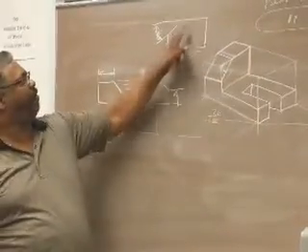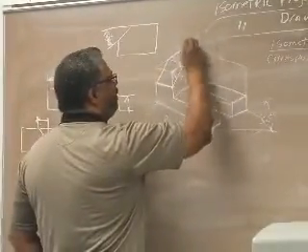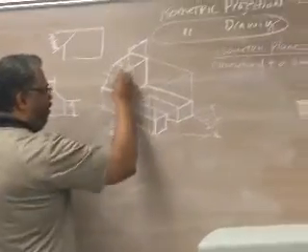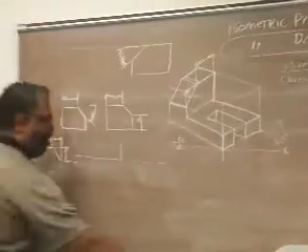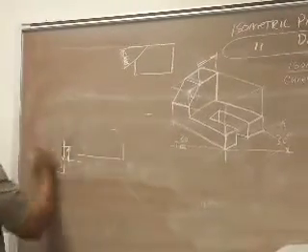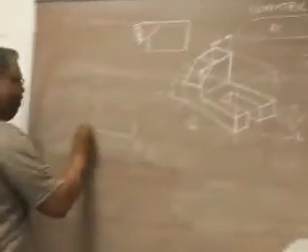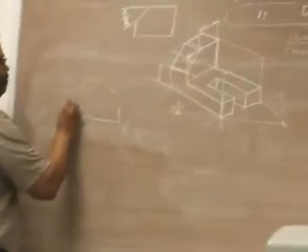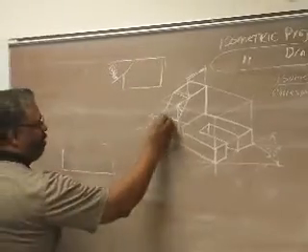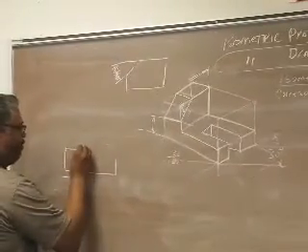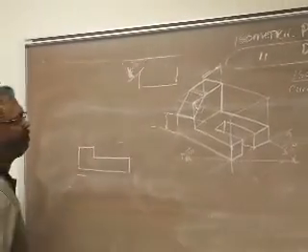So to get this angle correct here, whatever this distance is here, if I had this ISO, or whichever method you're going to use, that distance and this distance, then when I transfer that to my orthographic view, I can take this distance here, come up that distance, and so that'll give us that. So that'll give us this edge right here. And we'll call him like that. So that's that edge right there.